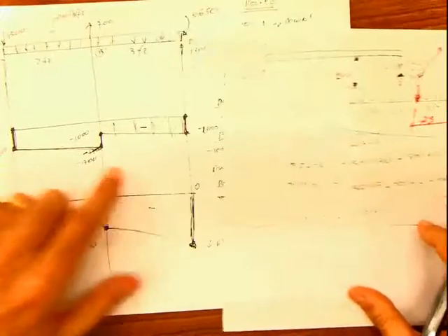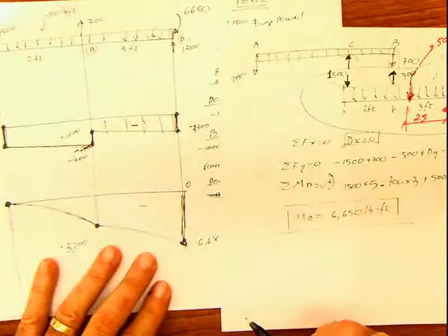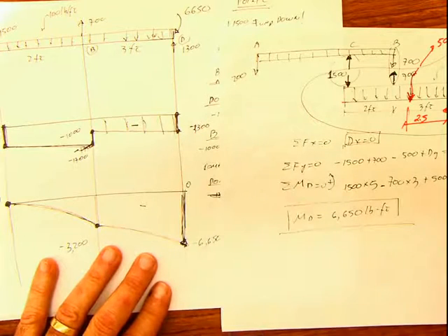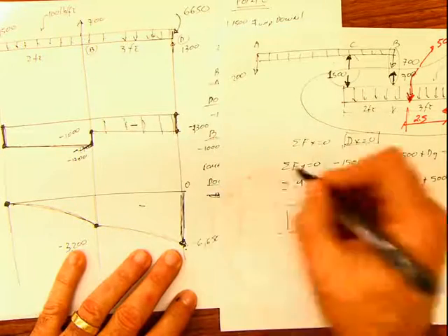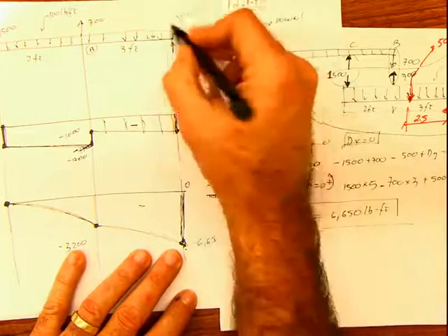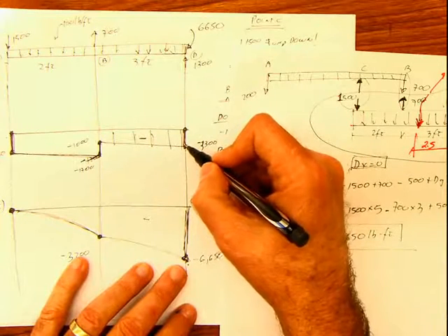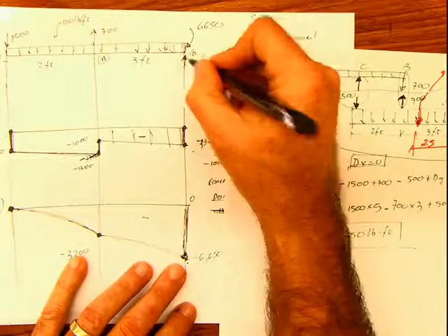Look, when we started from this end, we started everything from this end, and I didn't need those reactions until I reached the very end of the beam. So if I reach this point and I didn't have the reaction, I know that if the problem is correct, the only possibility for this to close in 0, if I am here at negative 1300, is to find a positive reaction pointing up.